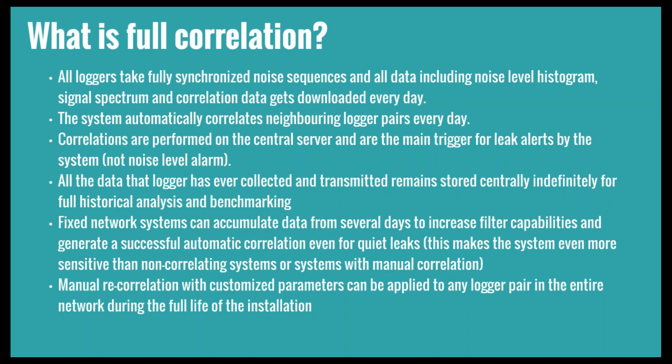So full correlation, a lot of words here, too many words actually, but basically a full correlation is all the loggers are synchronized, so they all are working in unison and listen together, and then it correlates pairs every day. So adjacent, when you set out 10 loggers, let's say in a mile stretch, they all correlate together, and then there's algorithms in the central server that trigger the leak alerts by system.